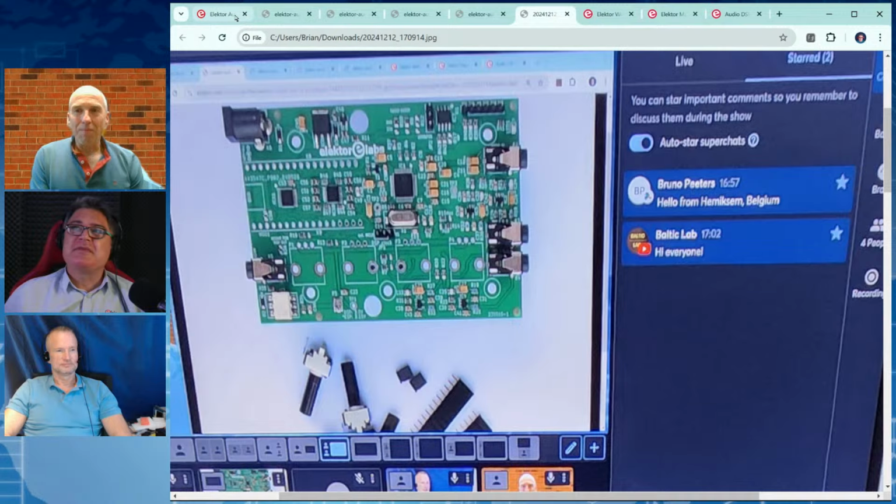But Clemens, how can you assure me of the compatibility between different MIDI sources? I mean, you've got the old-fashioned TTL, but you've also got the ESP32 running on 3.3 volts. So what are the dangers there? Well, normally there are no dangers because MIDI was designed to be safe, and that's why there is an optocoupler. So on the input, you can put anything up to, I don't know when the LED will break inside the optocoupler, but it's compatible with normal 5-volt MIDI.